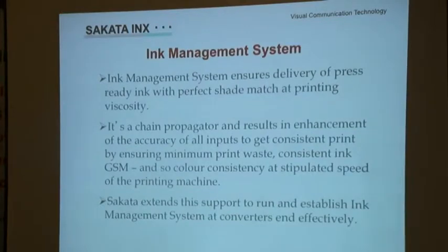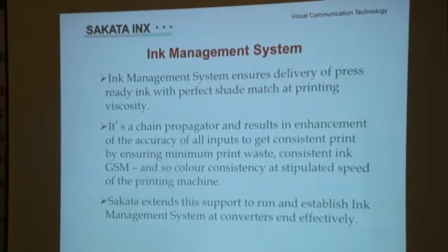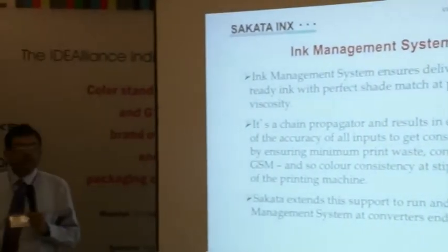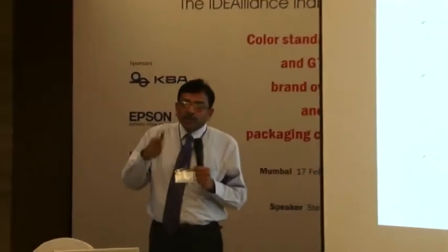Last time when we printed this particular job, my red ran at 22-second viscosity. So next time when I am going to print, I will be printing with the same ink at the same viscosity. Then only your color will be able to replicate. You will be able to replicate the color.